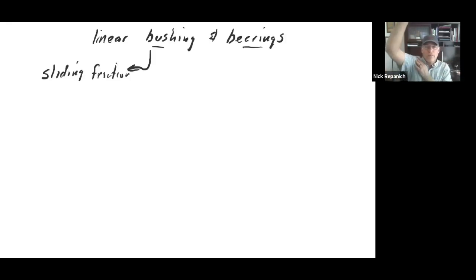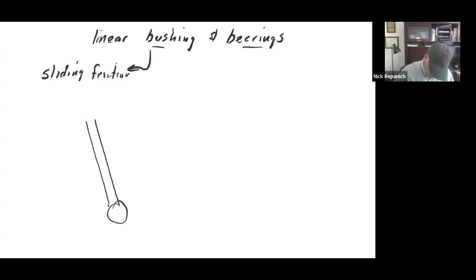The difficult thing about that is that if you want to actually program this point here to move a straight line in 3D space, your programming is all in polar coordinates. So you have inverse kinematics that you have to do if you want this point to go in a straight line. It's really easy to make something go, for instance, let's say you had an arm and here's your motor.